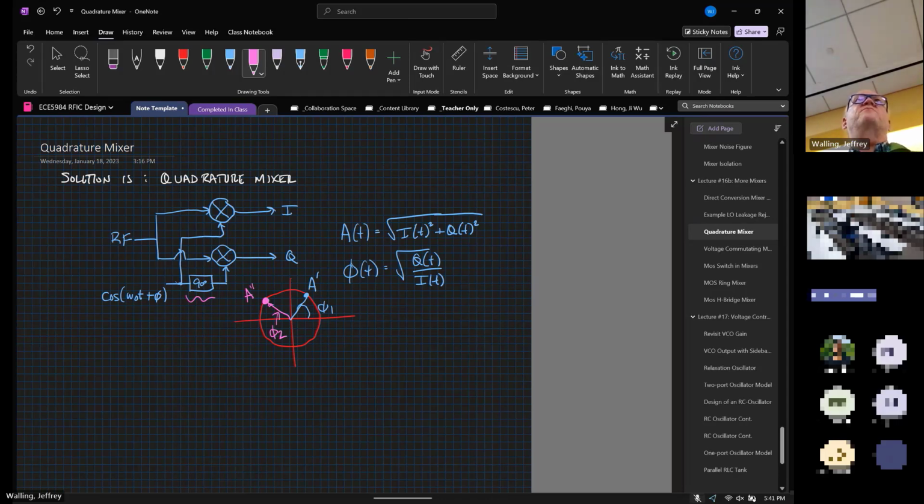So an oscillator that outputs 4 phases. And part of the condition of the oscillator that allows it to oscillate in quadrature is that the phases have to be constant relative to one another. So I can either use a fixed phase shifter that's equal to 90 degrees, or I can just make a quadrature oscillator. Most likely that's what I'm going to do.